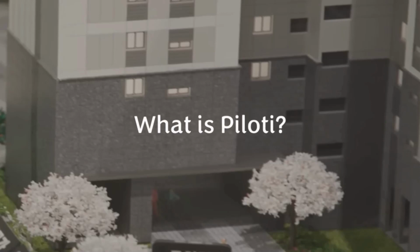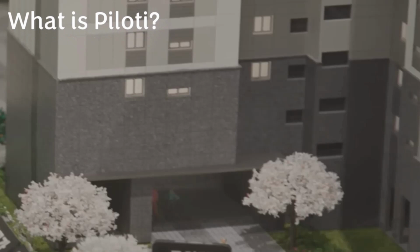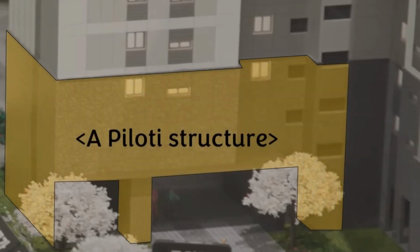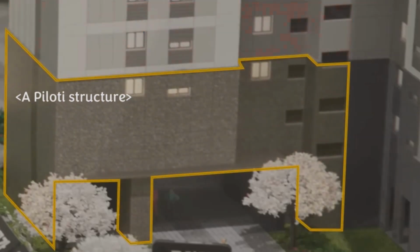Piloti is a structure in buildings with two or more floors where the entire or partial structure is supported by columns without external walls, allowing for an open space on the ground floor. While the upper floors have a wall structure, because of the piloti structure of the first floor, some or all of the wall elements do not extend down to the basement level, forming a piloti structure with beams and columns.